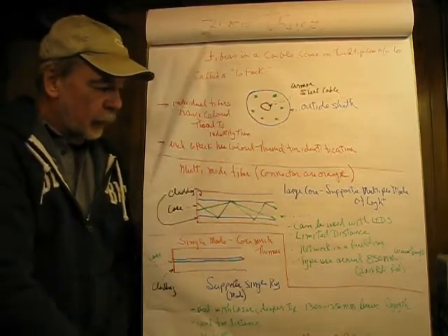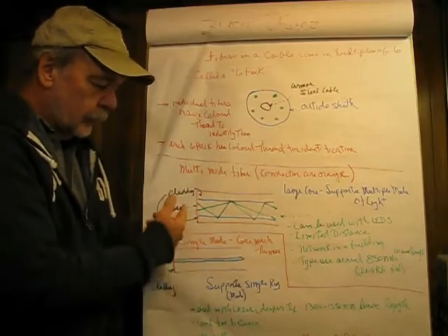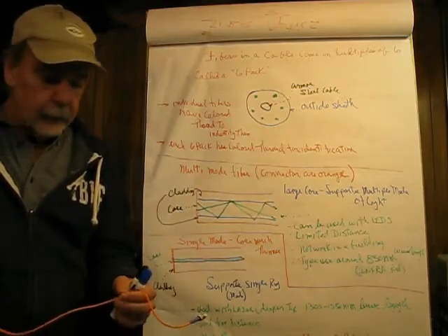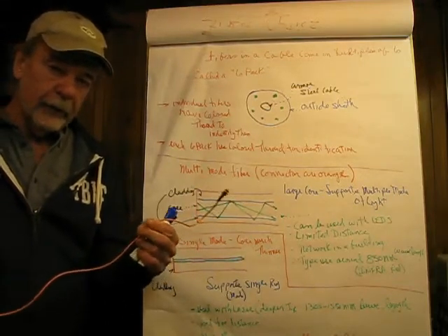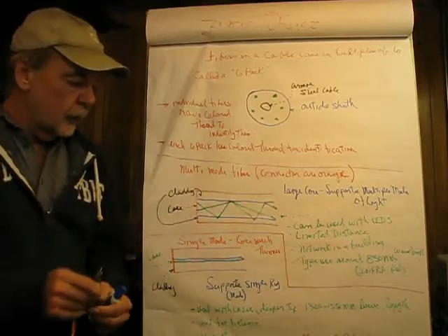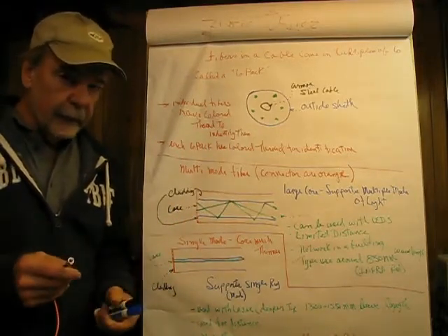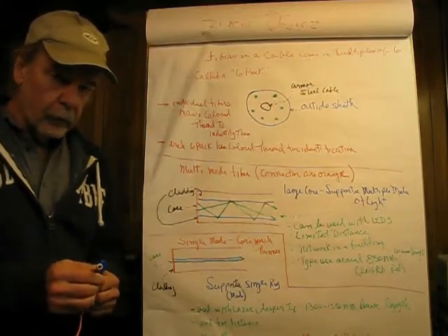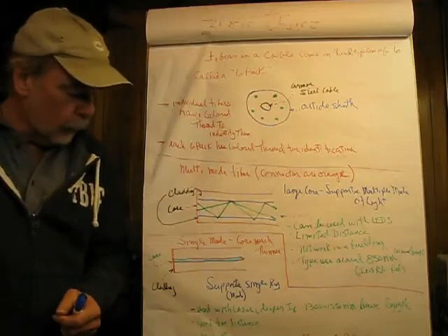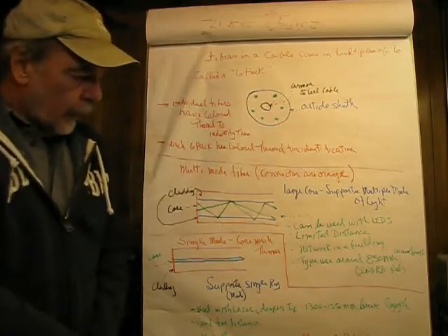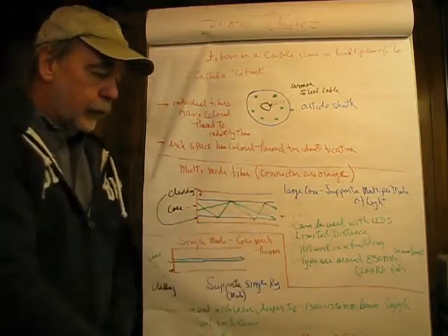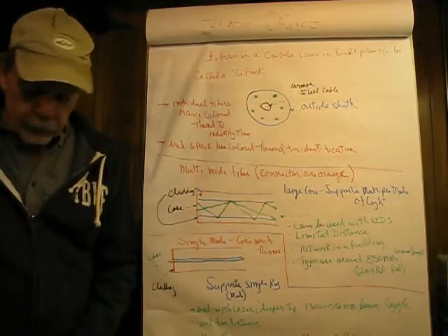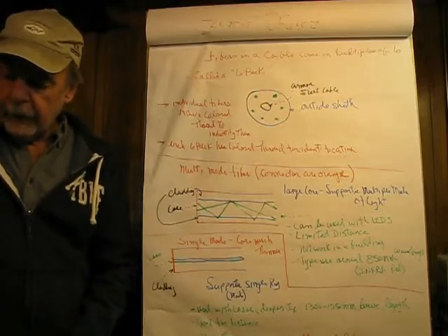Now, the color of multimode, especially, and this is the part that you'll typically be seeing, is orange, because we need an easy identifier for this, because once we have it, you're not going to be able to tell by looking at the core whether it's single mode or multimode. But a little bit more on that later. So it can be used with a light emitting diode, and that's kind of a good thing, because LEDs are significantly cheaper than lasers.